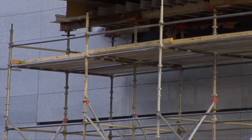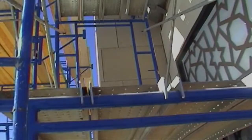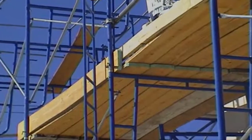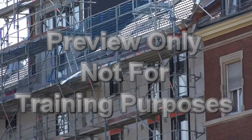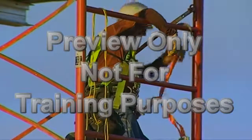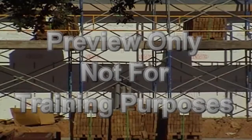No gaps greater than 1 inch are permitted between adjacent planks or deck units or between the platform and the uprights. Gaps may be larger if it can be demonstrated that a wider space is necessary. The maximum width of a gap is 9 1/2 inches. Platform edges may be marked for identification purposes only. Wooden planking cannot be covered with opaque finishes. Platforms and walkways must be at least 18 inches wide. In areas that are so narrow that they must be less than 18 inches wide, fall protection must be provided and used. Do not allow items such as tools, scrap, or material to accumulate on the platform and become a slip, trip, or fall hazard.